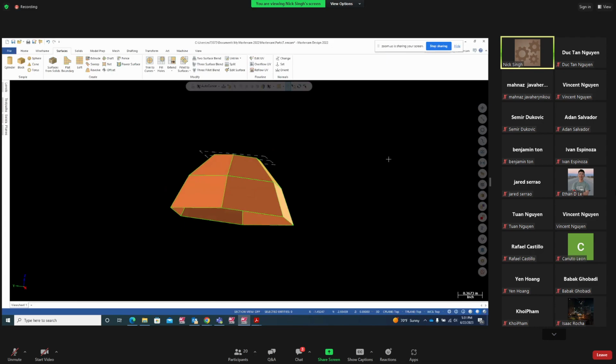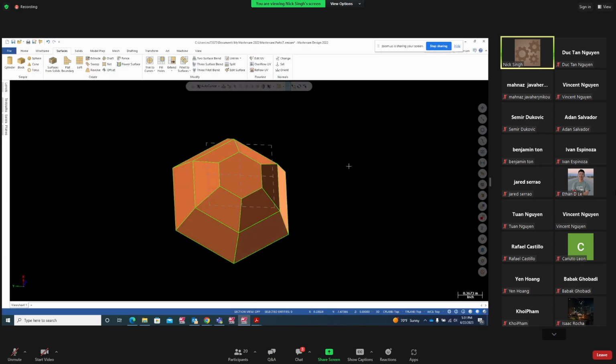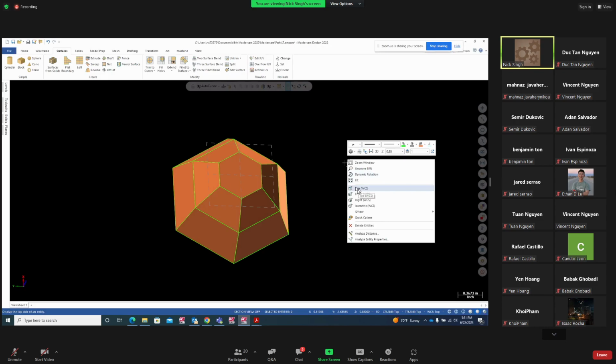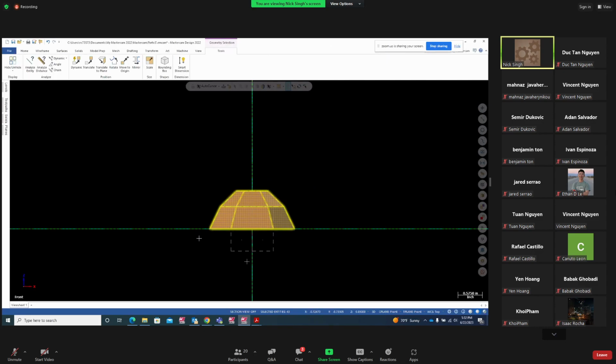Now we can go ahead and we can mirror that. So once we have finished the top surface, now we can go ahead and mirror the whole thing. We can mirror the entire thing, but this time we're going to mirror that. If you look from the front view, and I'm going to turn this axis on, whatever you see here, you want to bring this on the bottom.